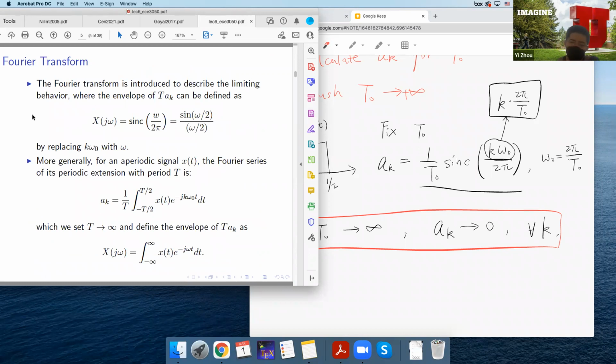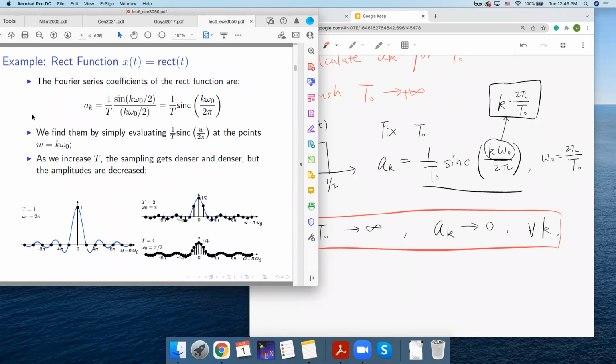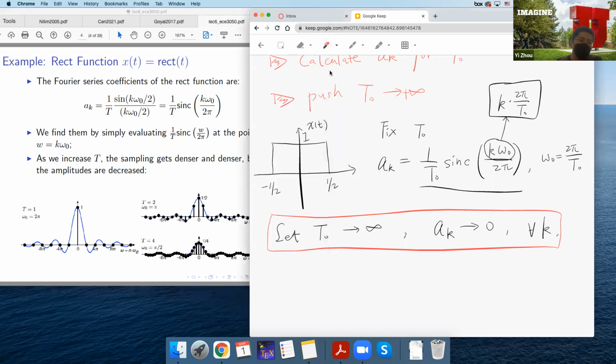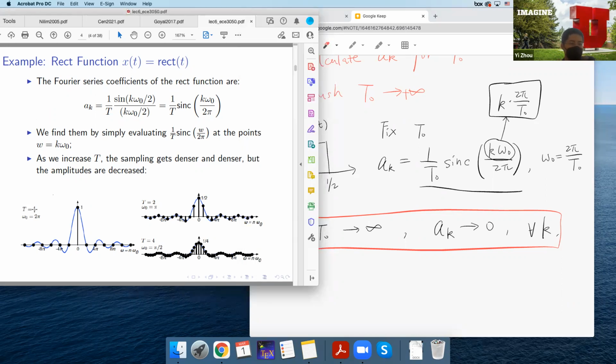That's a quick question. Yes. So is it correct to say that we still have the spectrum, but it converges to 0, and that's why we can't? Yes. So you can see from these pictures, right? For every finite value of capital T, we can indeed draw a spectrum. But because this is an aperiodic signal, the period is not finite. The period goes to infinity. When we let capital T go to infinity, the spectrum actually diminishes to 0, and that conveys no information to us. Okay.